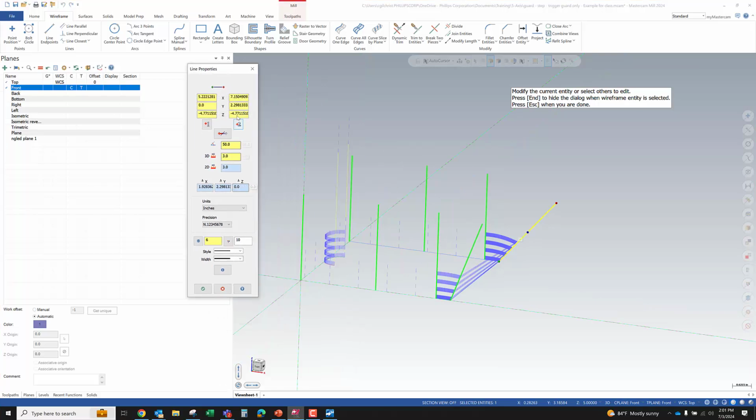The other thing I recommend you guys always do: make sure your precision is precise enough. 4 decimal places is never precise enough because there's always rounding involved, even when you're just creating regular geometry from the outset, but especially when you're dealing with customer geometry.